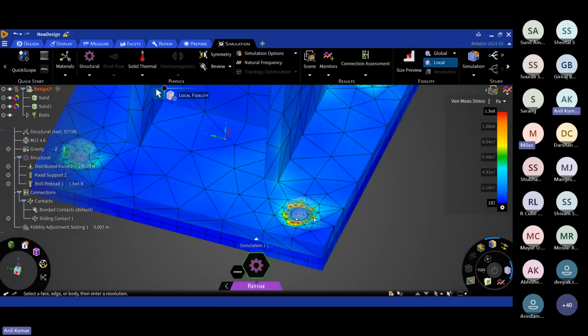Good afternoon, please. Actually, I wanted to know whether this software is capable of obtaining welding joint efficiencies, if I want the efficiency of the welding joint. So is this tool helpful for that? Sir, to perform a detailed study, you have to go to Mechanical Workbench basically for the welding analysis. But yes, for strength of the welding, we can perform that in Discovery also, the strength of the welds and all that calculation.